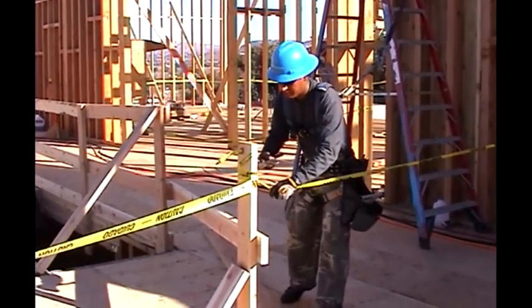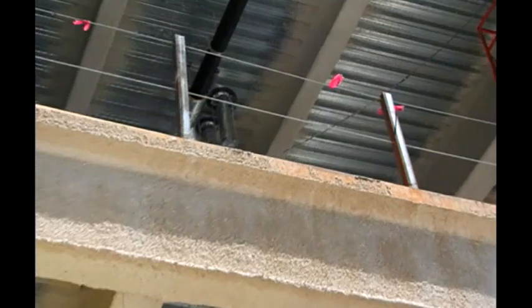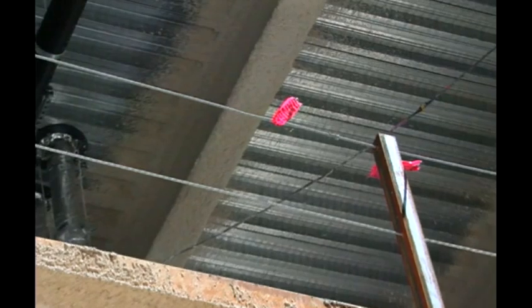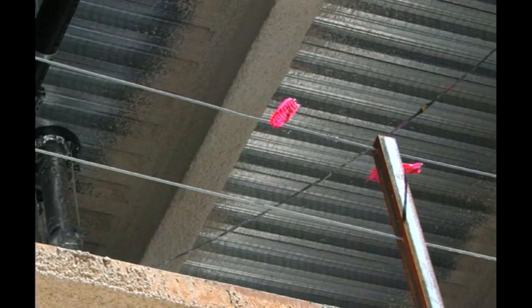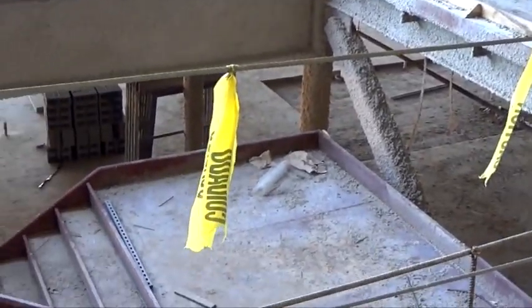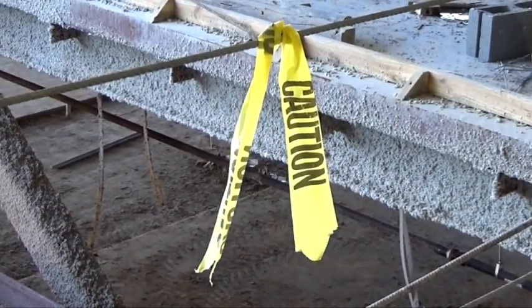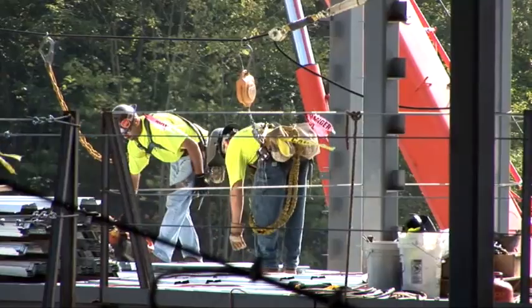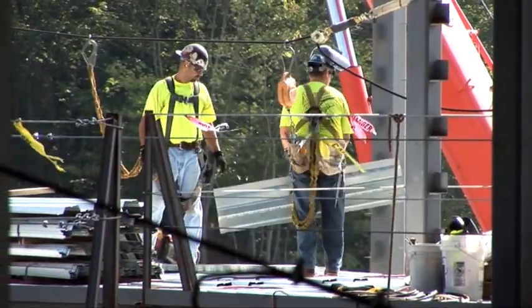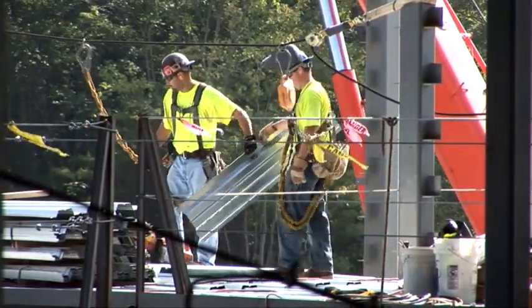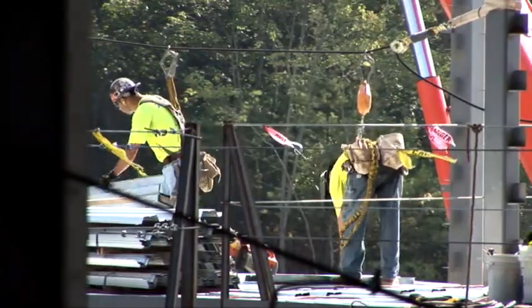Controlled access zones must be defined by a control line or by any other means that restrict access. Control lines should consist of ropes, wires, tapes, or equivalent material, and should be flagged or clearly marked at not more than 6 feet intervals with high visibility material. The control line must have a minimum breaking strength of 200 pounds. Other restrictions and rules apply. Your employer will provide you with the necessary information if this type of protection is utilized by your company.